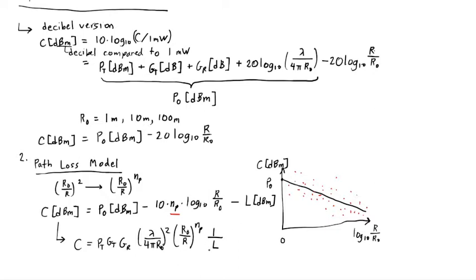So I would have 1/2 here in the linear formula. So when our problem statement says you need to account for this loss because it may happen, then I would use that dBm loss or that linear loss to compute the received power.